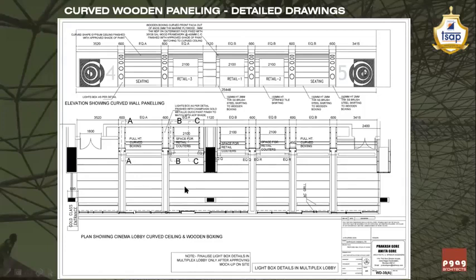Now, how is the contractor supposed to know how much this dimension is? If you give 2.4 dimension on this side and 2.5 dimension on this side, then whatever remaining dimension there is as per site condition will get compromised to the paneling of the door. So here the stagnant dimension is 3.4 and 3.5 on both the corners.